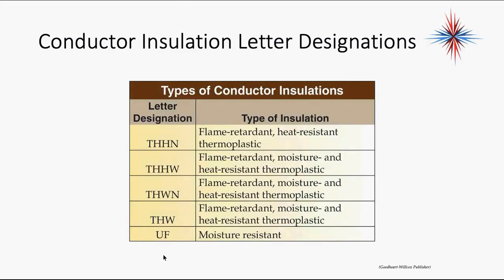Okay, conductor insulation is pretty important. You look at the roll of the wire you're using sometimes. You look at it, THHN is normally what we use. This is what I normally order for the shops, THHN. It's flame retardant, it's heat resistant, it's a thermoplastic.